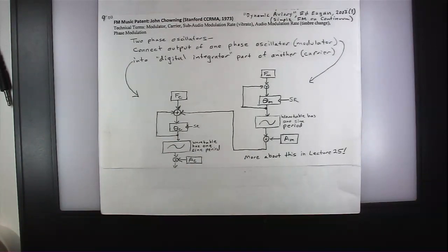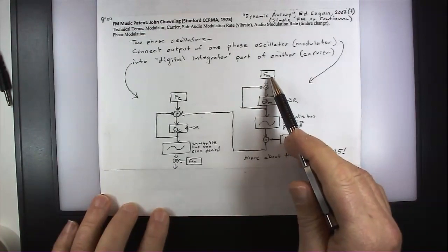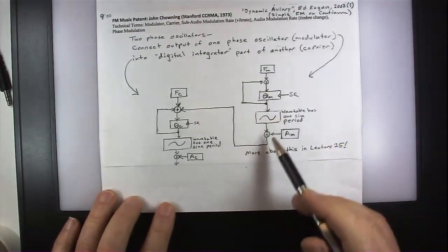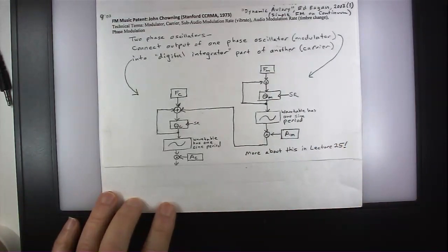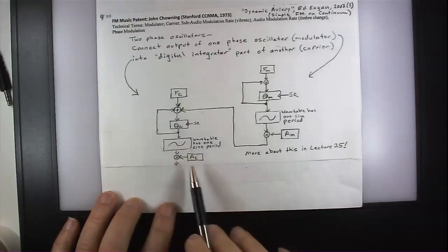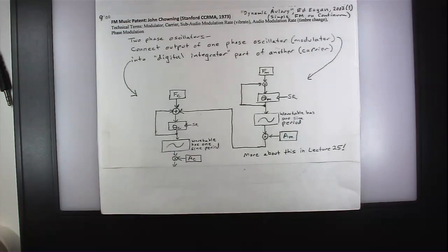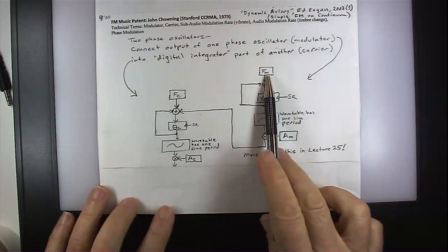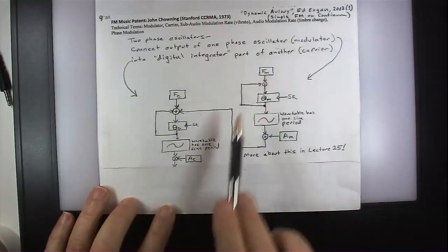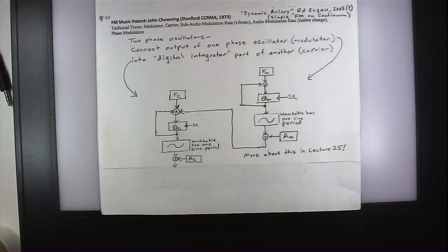Now, that's fine, but that's not what we mostly call frequency modulation. What we're talking about with frequency modulation is, what if this modulator is in the audio range? Now that's weird, right? If your vibrato speeds up to even a 10 hertz vibrato, you'll sort of hear it. And as your vibrato gets faster, though, you don't hear it as a pitch change anymore. You start hearing it as just a different timbre. It doesn't sound like a sine wave anymore. Now it's a distorted sine wave. In fact, if you look at it, you'd see a repeating waveform, and it doesn't look like a sine wave that's slowly changing pitch anymore. It just looks like a different shape. So that's what a very low FM is. This is just a low frequency oscillation. It's sort of like a vibrato. But as you go higher, what you end up with is a timbre change, a very useful timbre change.